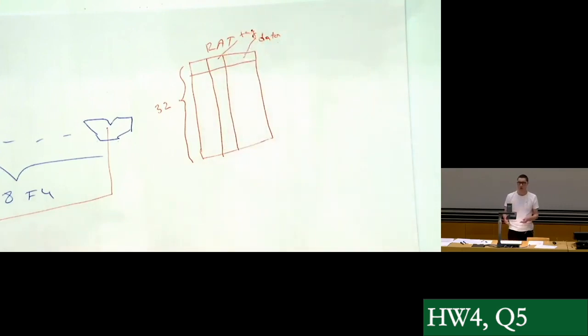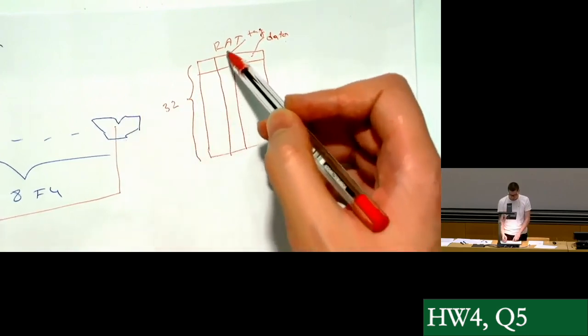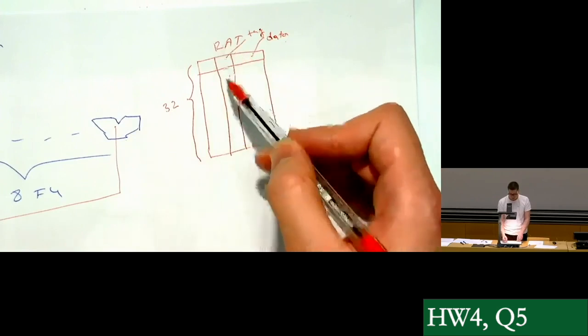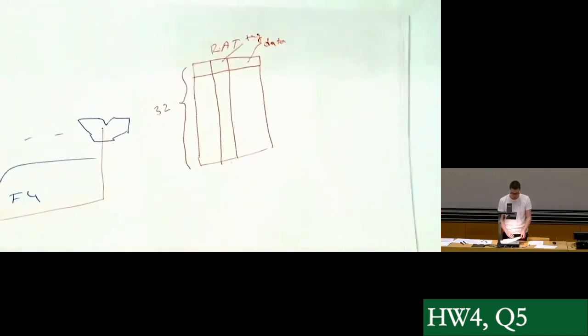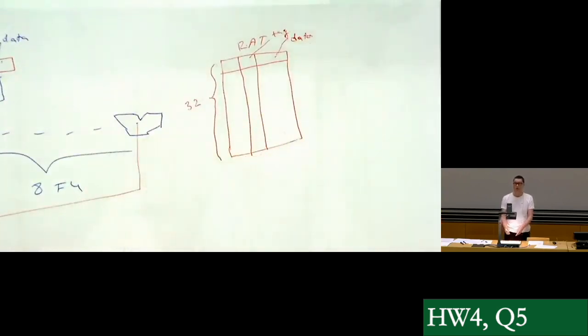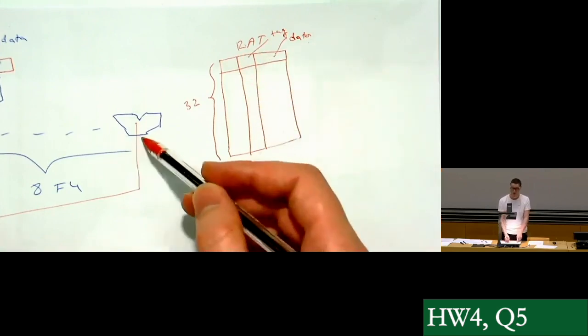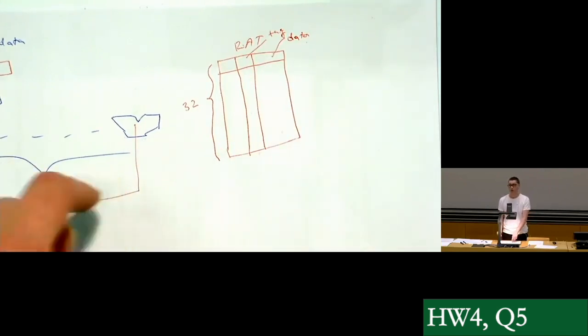And it will also have some valid bits. So basically, we also have some comparators here, right? So 1 comparator for each tag. And then it will again be multiplied by the number of functional units, because in a single cycle, we will need to compare those tags against each of the results coming out from the functional units.